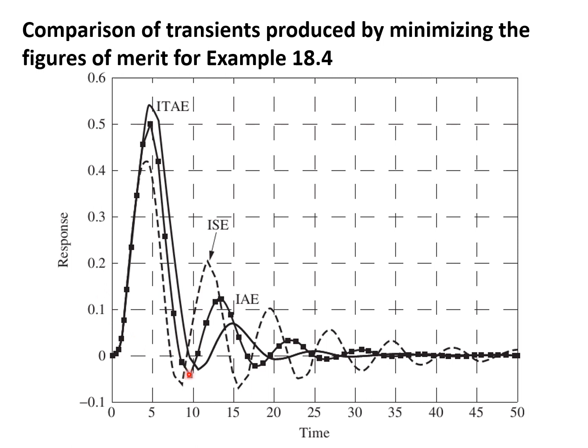The ISE has less overshoot, but a little bit more oscillation. Going down, the IAE, which is the black one, has higher overshoot, but slightly lower oscillation further on, and better decay. ITAE has high overshoot, again quickly decays and goes down to the final value.